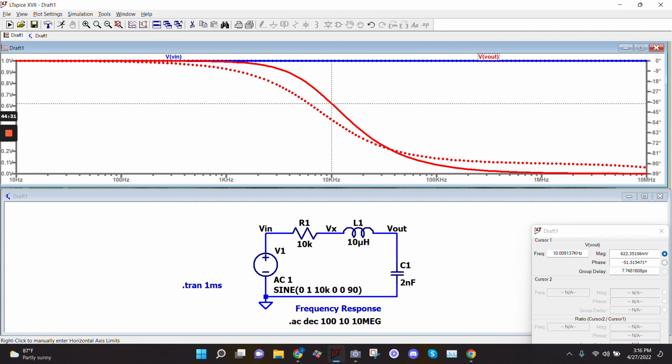So when we add them in series, all we get is the R. There is a frequency in every RLC circuit called the resonance frequency, and that is the point at which capacitors and inductors cycle charges into and out of one another, and there's a loop of energy happening.